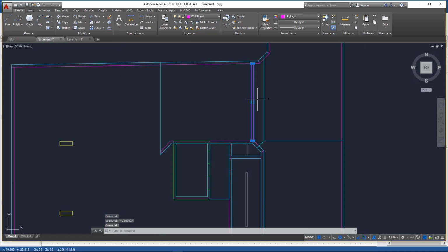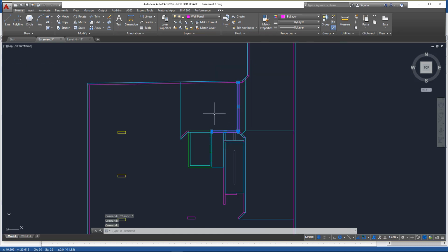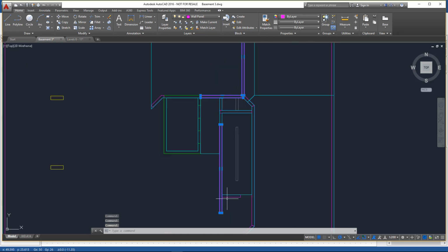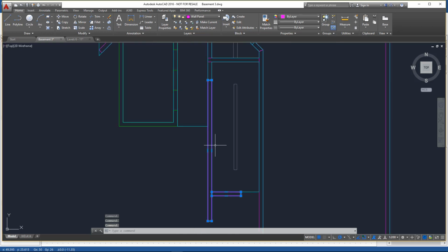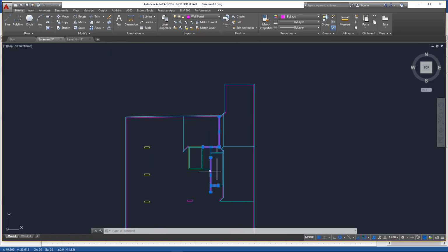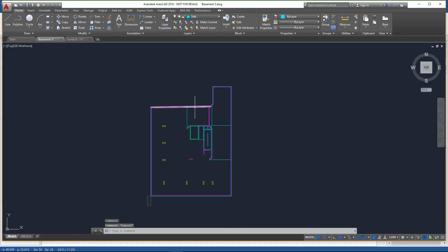And these individual walls have been drawn as segments, so these are going to be precast panels. So we see here we don't wrap a polyline around the entire wall because there'll be a discontinuity, there'll be no connection here, hence why they've been modeled like this. The other thing that we've done on this floor, which should be done all the time, is we've drawn a single closed form polyline wrapping around the perimeter of the slab. So just wrapping around the entire perimeter so that there's basically no chance of the mesh being generated incorrectly. And we've got a few areas here of different loading.